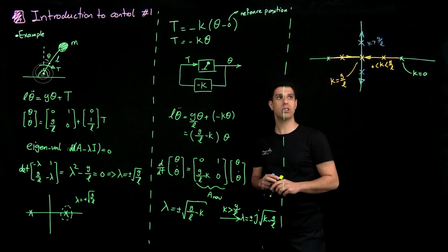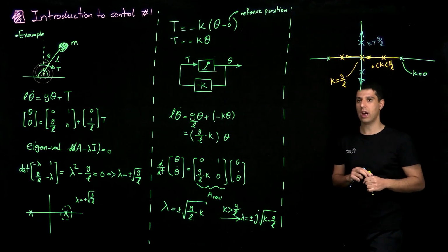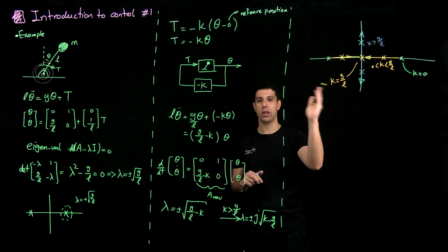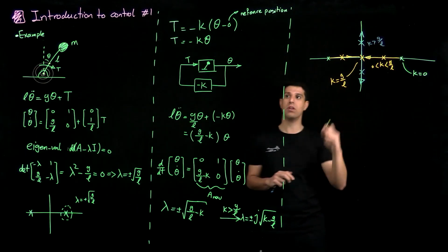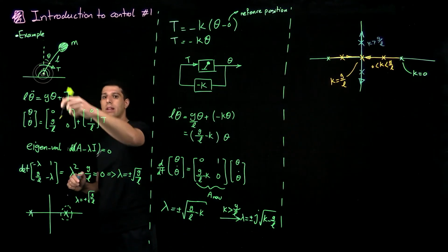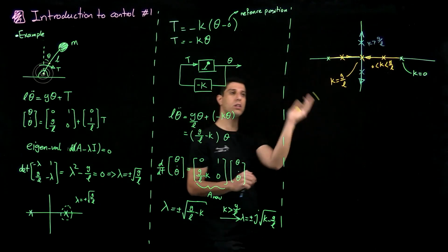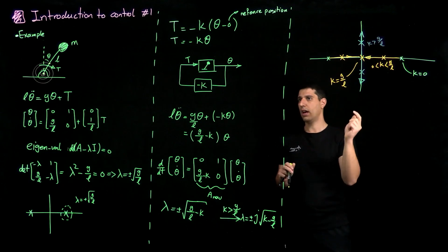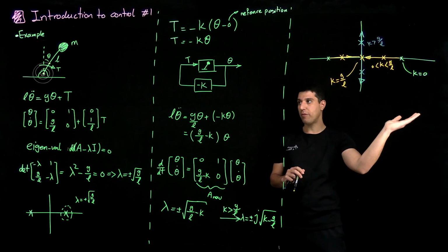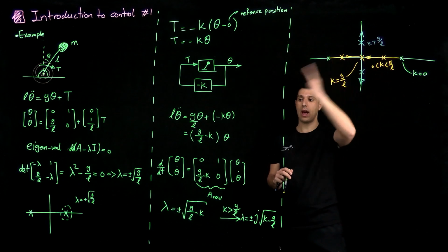It is marginally stable. If you remember, if the poles are on the imaginary axis, we have marginal stability, and the system essentially oscillates back and forth forever without dying or diverging to infinity. This is expected from a system that has just a spring, so there's no energy dissipation, so it will continue to oscillate forever. If you perturb it, it's going to move to a different amplitude of oscillation, but it will continue to oscillate with that new amplitude.